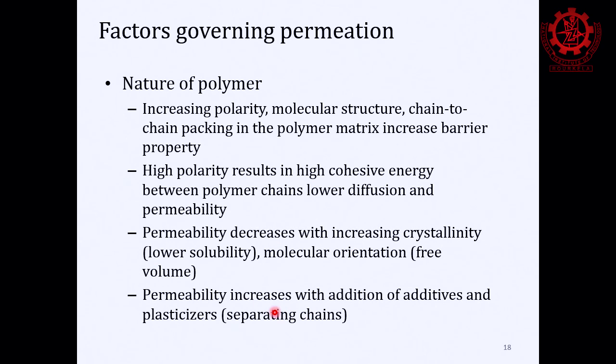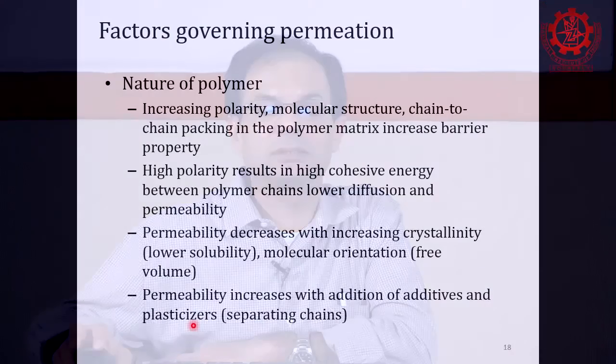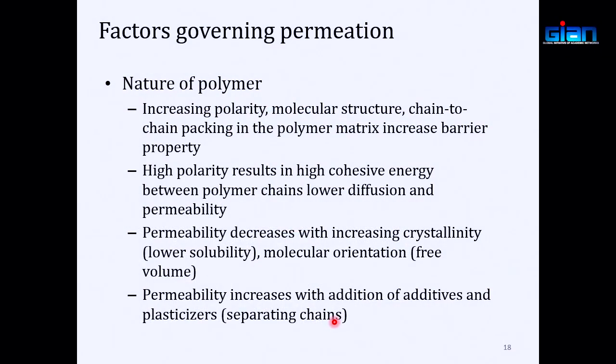And of course, you can allow some addition of additives in the polymer. What kind of additives do we have in polymers? Do you know additives and plasticizers? Actually, the native polymers like polypropylene or polyethylene, all these polymeric resins, it is still not very easy to stretch into a film. So we allow some additives into it to plasticize that polymer.